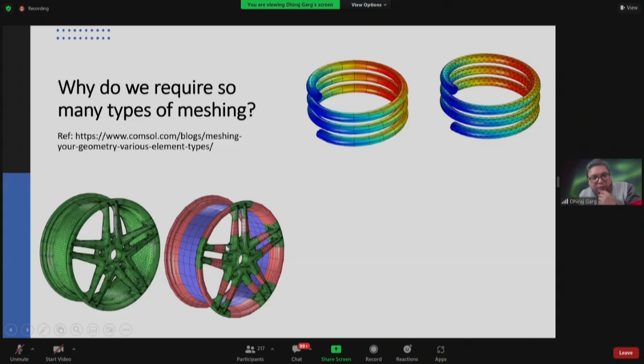In the case of turbines and such rotary dynamics, we can apply a cyclic boundary condition, knowing that the outlet of one side becomes the inlet for the other. But if in this case the process is not symmetric, let's say there is a force in this direction only, then we cannot use the symmetry. So we have to be careful while exploiting the symmetry.